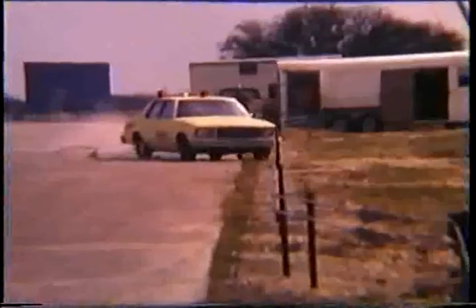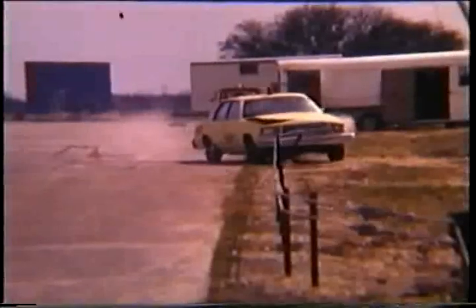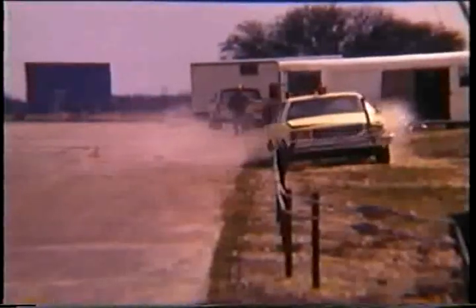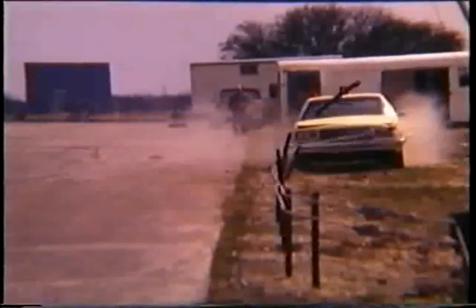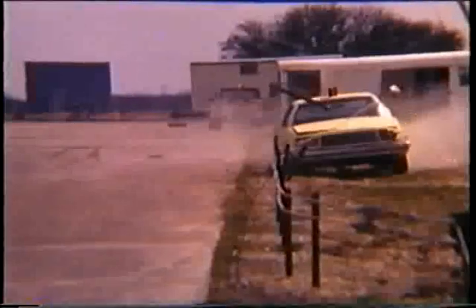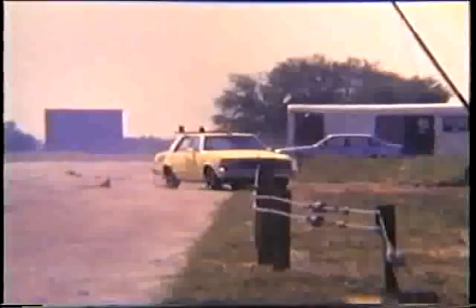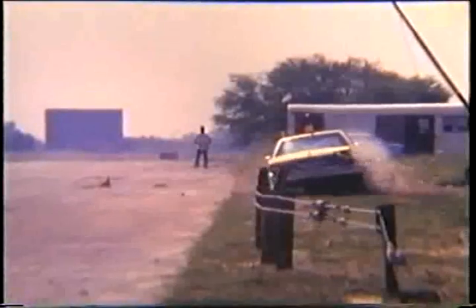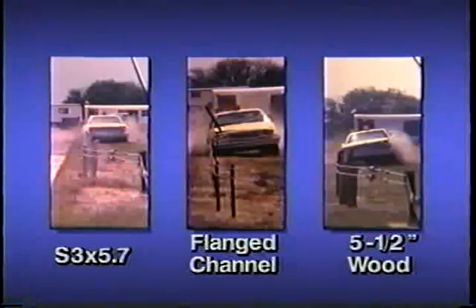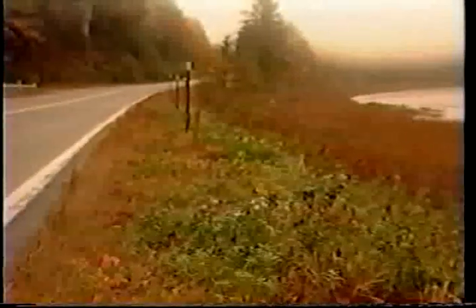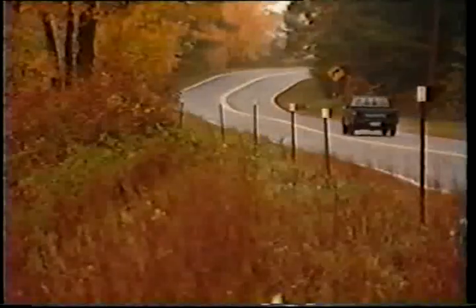The flange channel posts tended to fracture easily, and some were thrown back into the roadway. The cable in the flange channel post system rode over the top of the vehicle, so its performance was considered acceptable, though not desirable. Information on these cable guardrails and warrants for their use have been developed in NCHRP Project 22-5A. These systems could provide a cost-effective guardrail on lower service level highways that would not otherwise be protected.